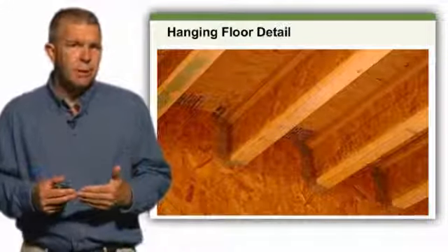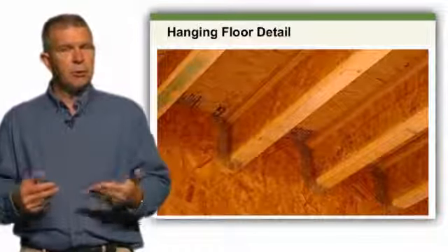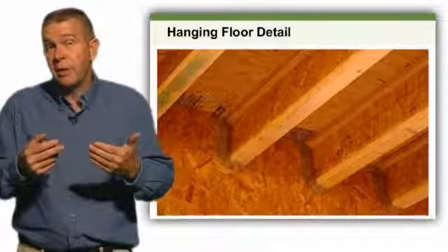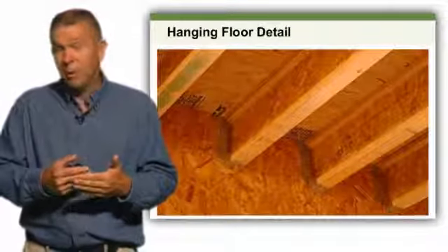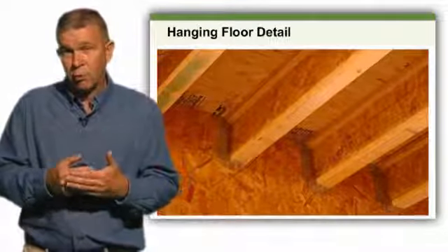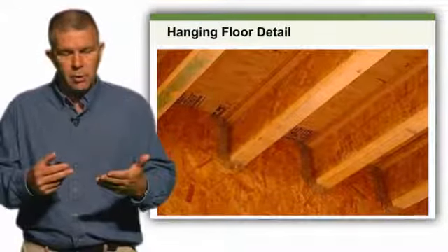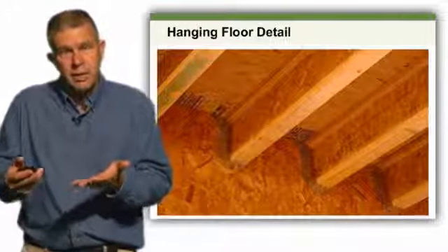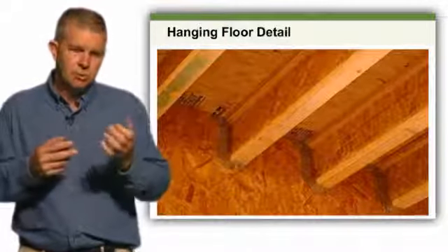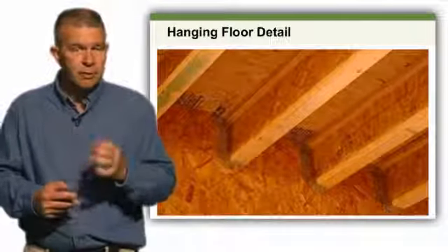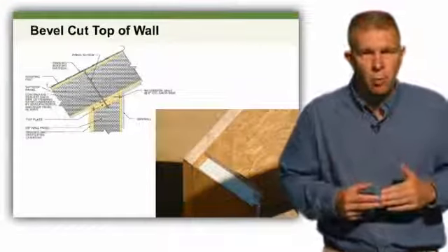The thing that you need to be aware of is when you do a hanging floor system, in some cases you have concerns about moving your electrical from one system to the other because you don't have the advantage of dealing with that floor system to work inside of. But one of the big advantages that the hanging floor system also gives you is it increases the diaphragm capacity of that connection between the floor sheathing and the wall itself. It's a great system. It goes up just as quickly as a platform frame system, and from an energy standpoint, it can't be beat. Let's continue working our way up this wall panel.